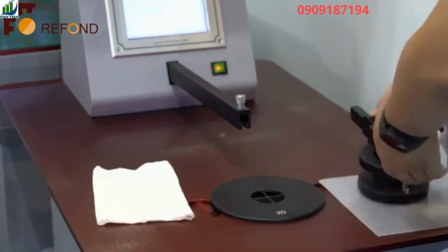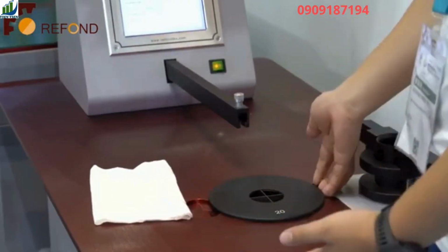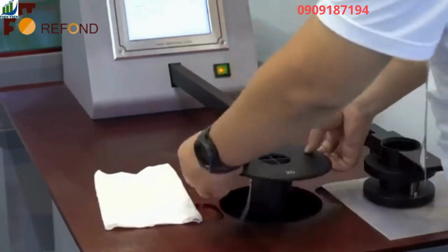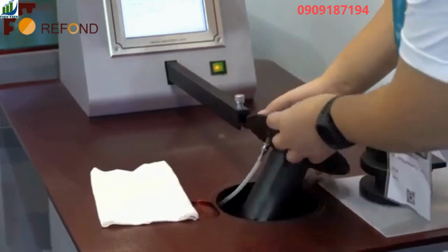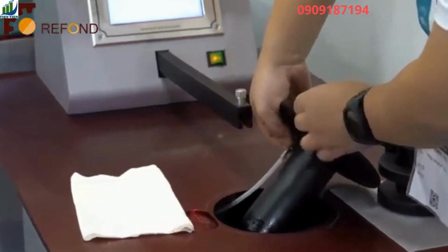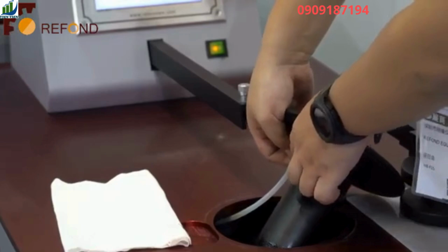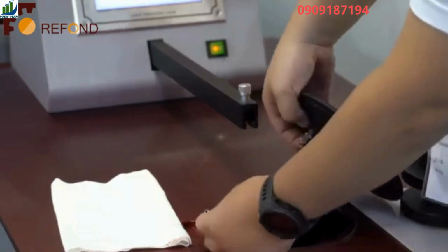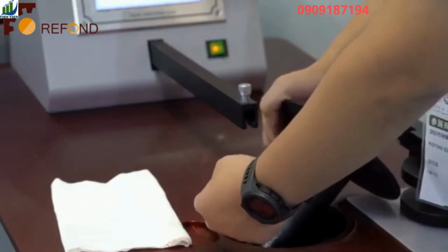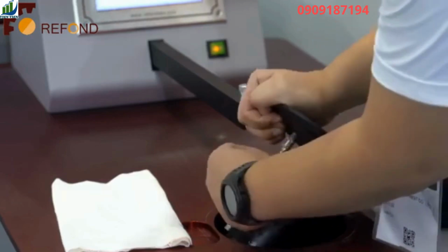To remove the bottom test head, you just need to put your finger on the side of the test head and then lift it up. There is also one pipe under this test head. Pull on the little knob on the connector here to release the pipe. Then to put on a new test head, you just connect the pipe by pushing it into the connector.